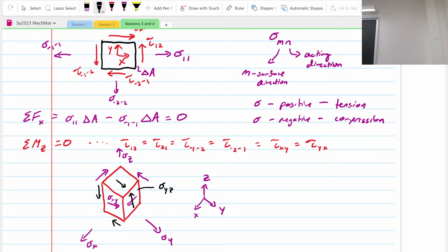But one way to think about this is, now this is one member. Remember how we just found that this member is along for the ride? What's the force in this member? If the only two forces acting on this are from the wall and from this F2, what's the force in this member? Or what's the internal force, just for this purple region?